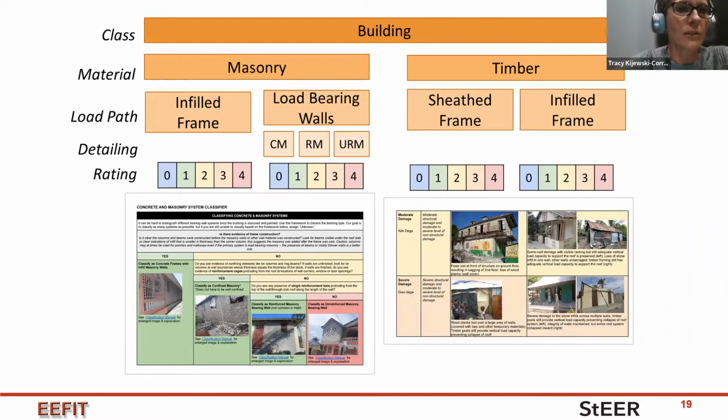And then we further customized the guidance to step through, as you can see by the two screenshots on the governing instructions given to our assessors, to help them understand how we would first classify each of these primary systems into their specific typologies, and then how we would recommend the evaluation of damage, assigning an equivalent EMS 98 scale to map undamaged to complete collapse along this 5-point scale. All of that guidance was prepared, and we developed instructions in both English and Creole, and made this as well as some training videos available to help our assessors.